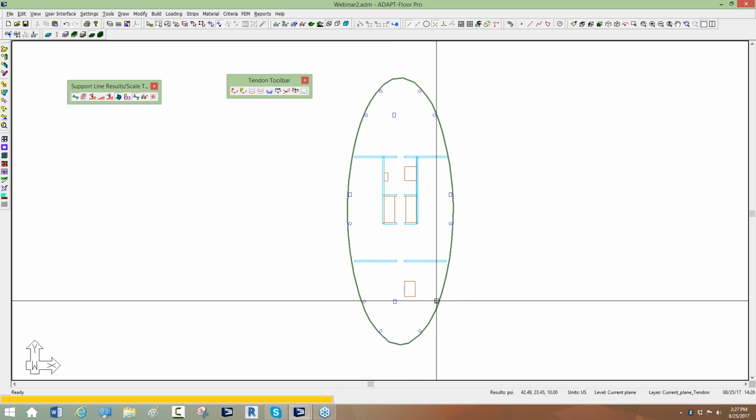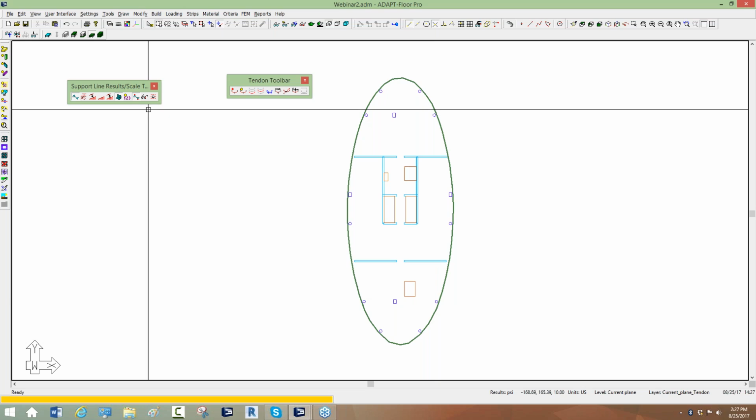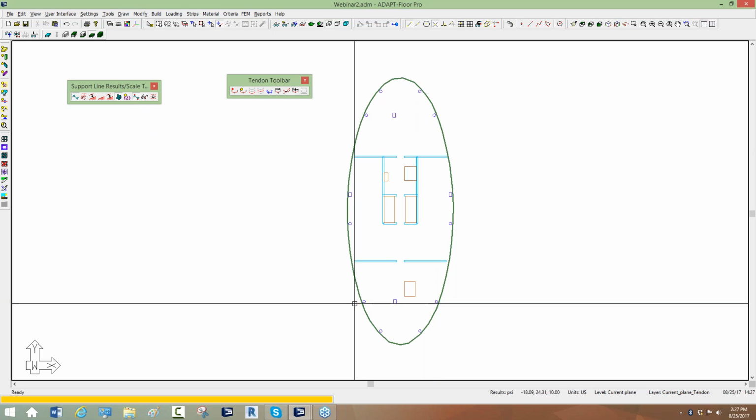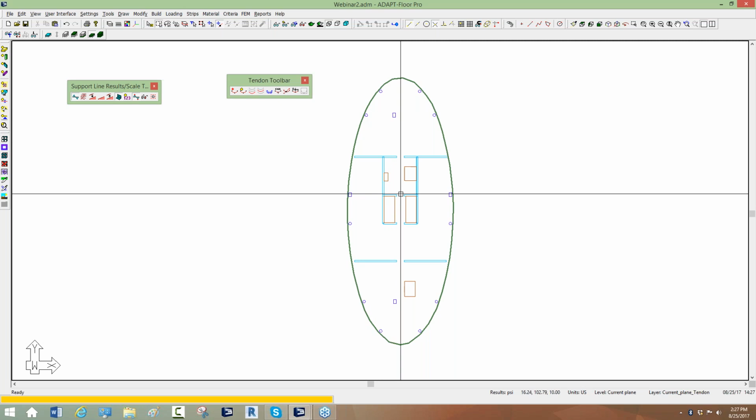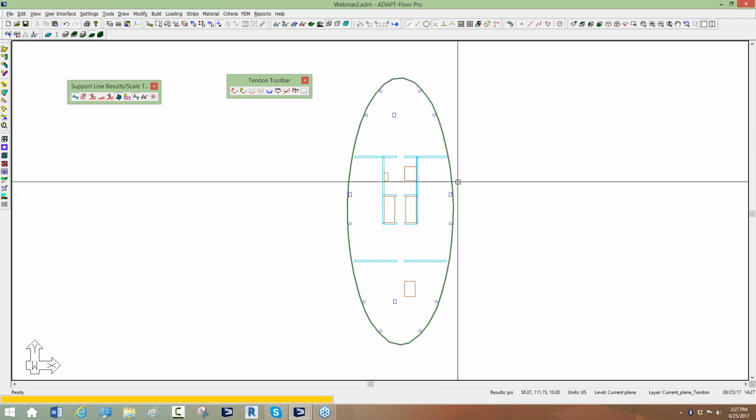For uniform tendons, because we assume the bands are basically virtual supports for the uniform cables where we're distributing load from uniform to banded, we don't technically have to follow the line of the supports. We could go in here and actually model uniform support lines across the width of this model for our uniform tendons. But in this case, we're going to use mapping. We'll map banded. We'll model the uniform as banded lines. So we have to have some support lines to do this.